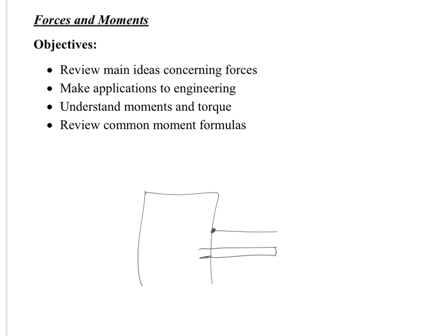That's cantilevered. So something that's cantilevered can resist a lot more moment or torque than something that has a pin fix. A pin is easily rotating. It's usually actually free to rotate when there's a pin. You can lock a pin in several directions, which will cause it not to rotate, but generally something that's cantilevered has more strength in rotation. All right, let's go right into it.